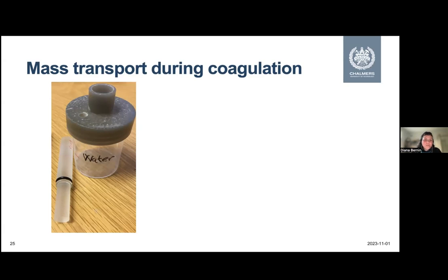You have to dissolve the cellulose and also the lignin. Here it's aiming at making bio-based carbon fibers. So you add the cellulose-lignin solution here. You get a film on this piston. You add this piston, and then you add water or any other solvent, which is an anti-solvent that makes the cellulose coagulate. And we believe that